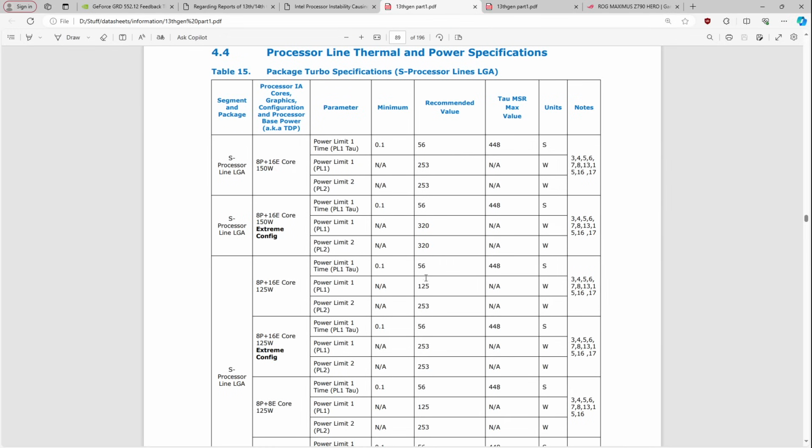Now, if you set the power limits, the CPU will power throttle before it thermal throttles, and so you're going to run at somewhat lower frequencies, and it'll not crash because it's running at lower frequencies at lower temperature, because it's power throttling before it hits the thermal throttle point. So that's a few different ways to fix it. If you're really unlucky, even just setting the power limits to the Intel recommendations won't be enough, in which case, again, you might just have to raise the core voltage.